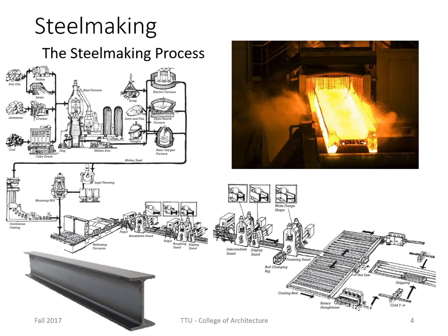So that molten steel is processed and mixed with existing iron ore. And so we have molten steel now. So we come out of the blast furnace with molten iron and add it with maybe recycled steel, or we turn it into steel through a basic oxygen furnace or an open hearth furnace. Open hearth furnaces are not used as much anymore because they're not as efficient as a basic oxygen furnace.